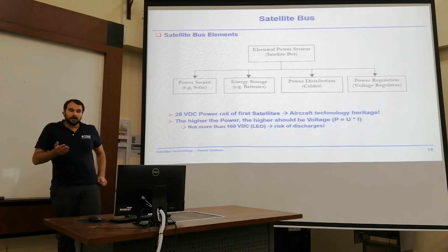And in the case of a nuclear power source, the solar array will only be the secondary power source. The S3R regulator is required to control the bus voltage if the load demand is lower than the power generated by the solar array. And that means this topology offers the possibility to recharge the batteries without using a battery charge regulator.